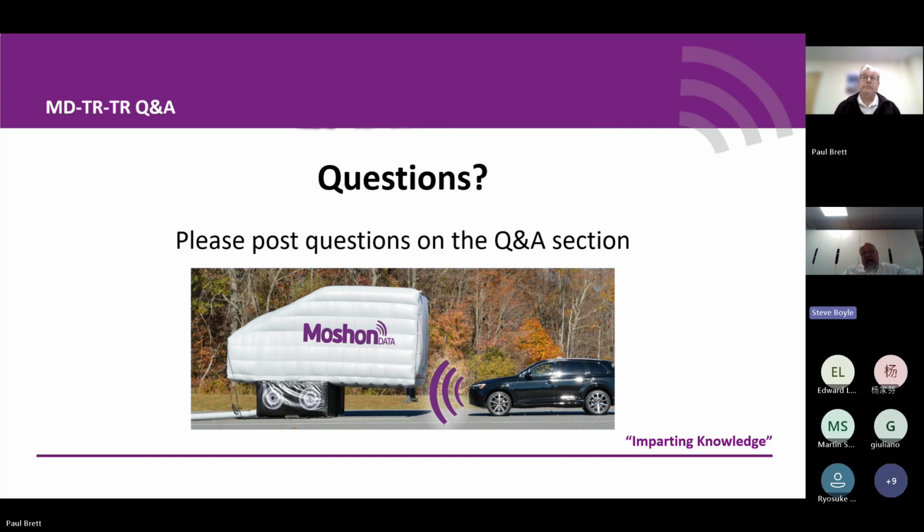But as I said, the initial design and the initial tests in the world at the moment for AEB on trailers and truck trailers is from the rear. Pretty much like we started with the CCRS for the AEB in 2013. This is like the next phase of that CCRS, except it's not car-to-car rear stationary, it's car-to-truck rear stationary.